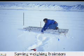But we were concerned about the snow bridging between the load being carried by the lysimeter and the surrounding areas. So every time there was a snowfall we would span this ladder across it and saw around the edges with a saw to try and make sure there was no bridging, and the weight being measured was only the snow on the lysimeter. So that shows it after we'd sawn it, and I guess there was some disturbance because there's a crease there, but I guess you can't measure anything without disturbing it. Who was it? One of the famous physicists figured that out.